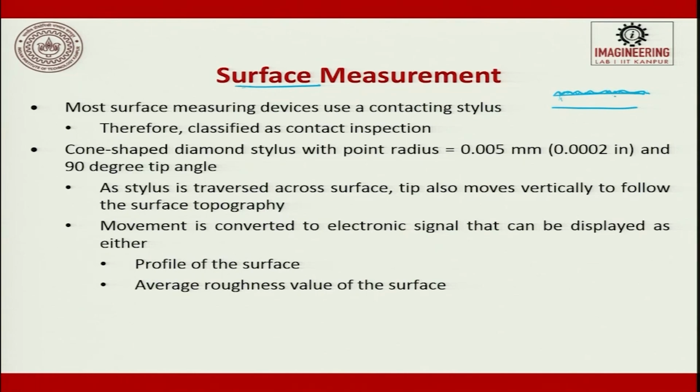So, here we would also like to measure the surface. When we want to measure the surface, we have to take continuous contact data. We are talking about the shop floor level. When we talk about STM, the scanning tunneling microscope, again it is non-contact and very small, but you have to take the data all across the surface. Whereas in CMM, generally what we used to do is take a lot of point data, and this point cloud data will be converted into surfaces. That is the difference between CMM data and surface data. In the latest advancement, CMMs have also started taking continuous data. So, today's CMM machines, whatever comes into the market, can also be used for surface measurements.